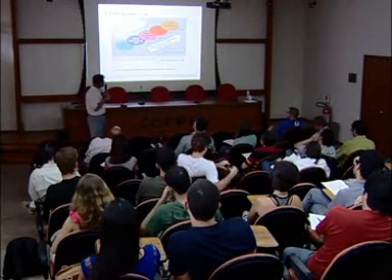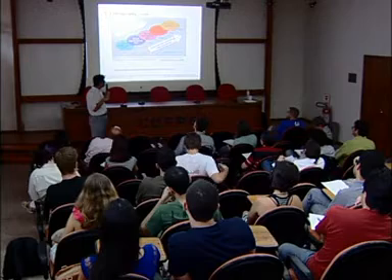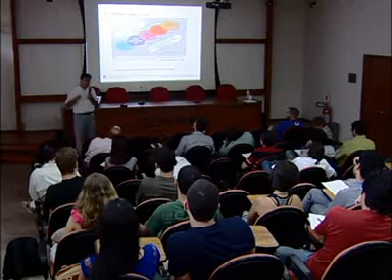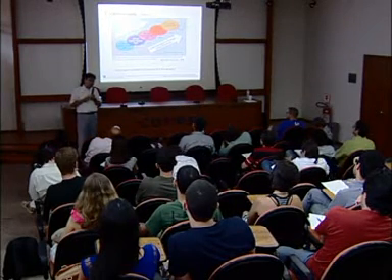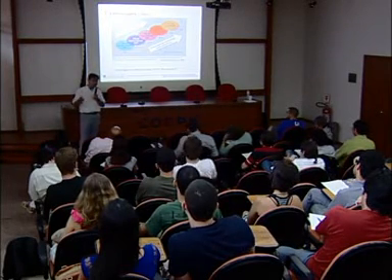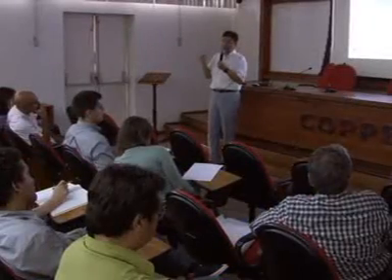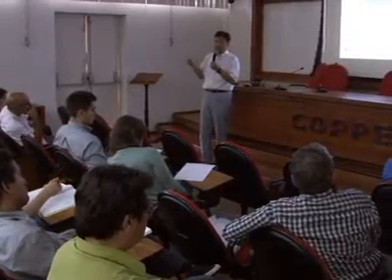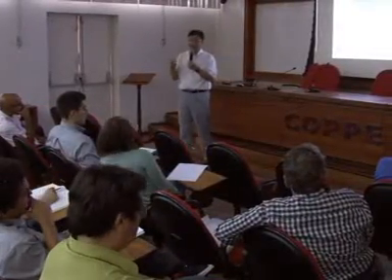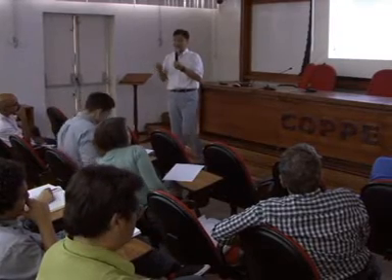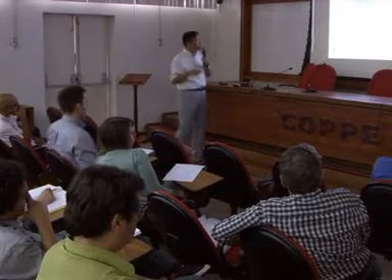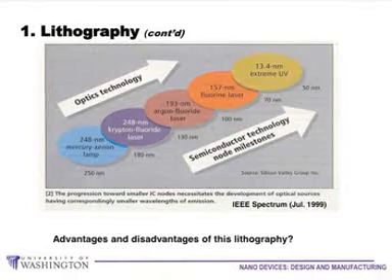Yield of semiconductor fabrication at a very small scale should be over 70%. Then it's commercially viable. If it's less than 70%, even though I can make some patterns, those devices cannot be produced because of the high manufacturing cost. So now semiconductor companies are competing with this small wavelength.